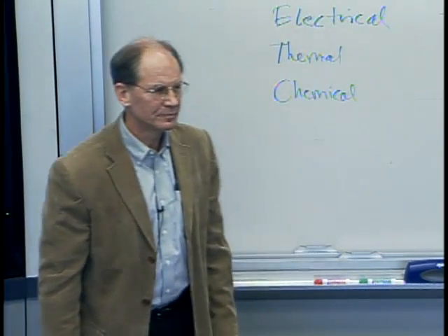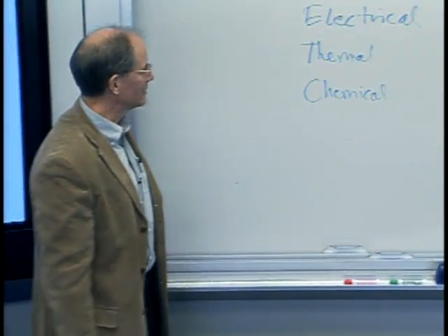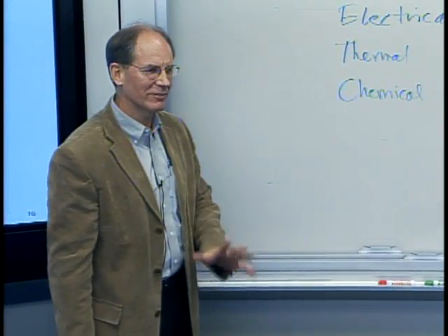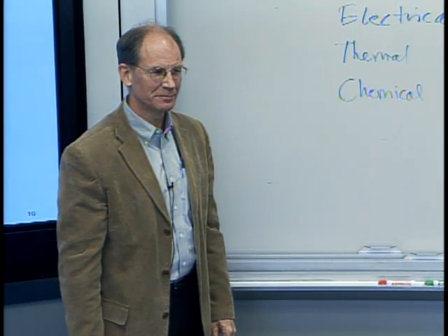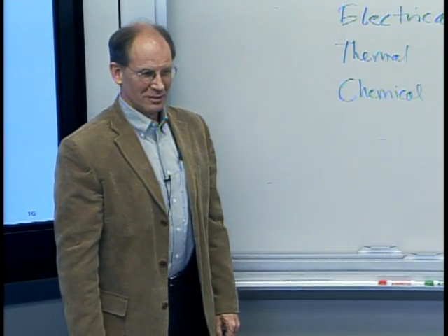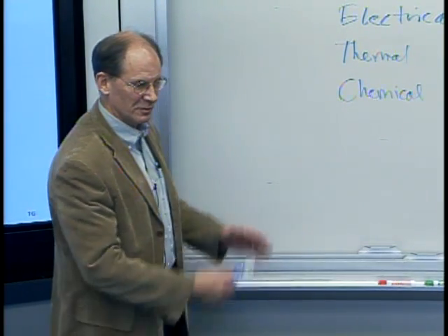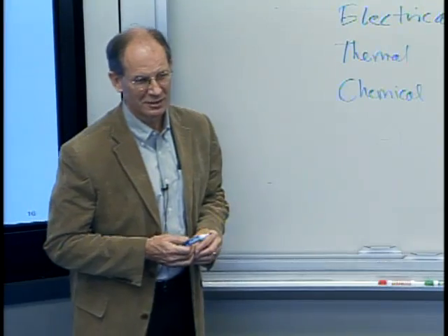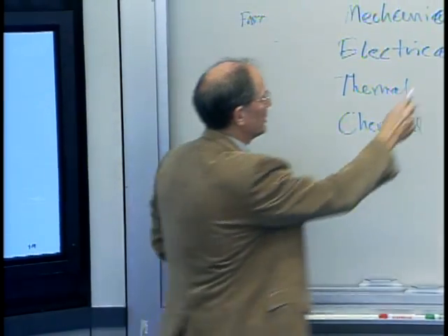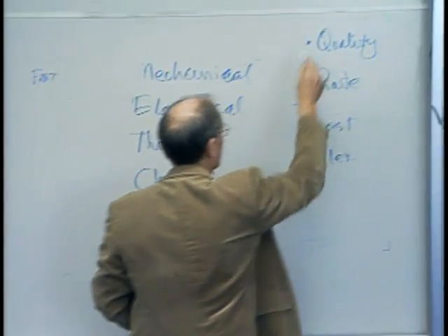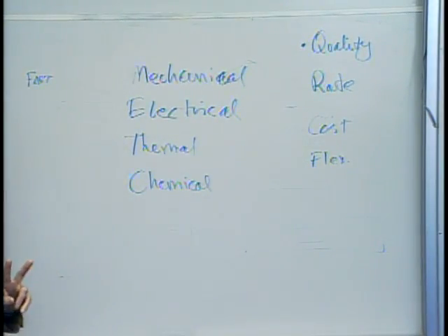Tolerances are also side effects of the process. Yeah, say a little bit more about side effects. Well, you've got the theoretical, maybe I want to cut a perfect square, but the tool's not going to cut perfectly square edges. So depending on what process I use, it may have undercutting or rounded edges. Absolutely, absolutely. So there's something here inherently related to quality. At least two things that I can think of.